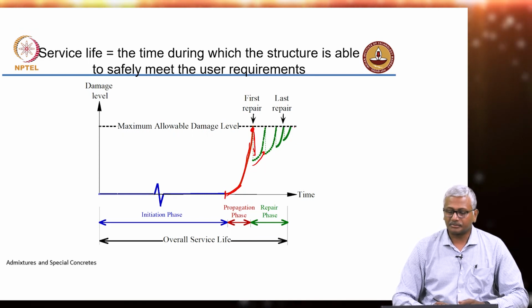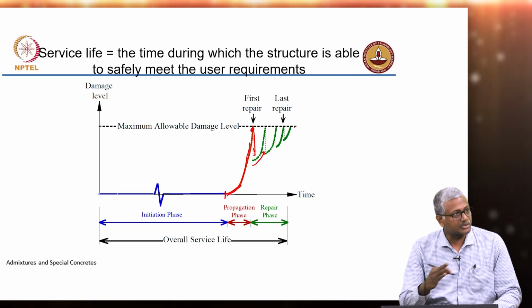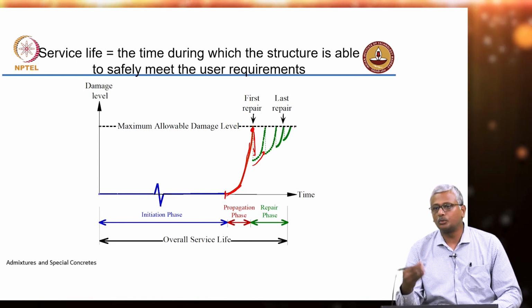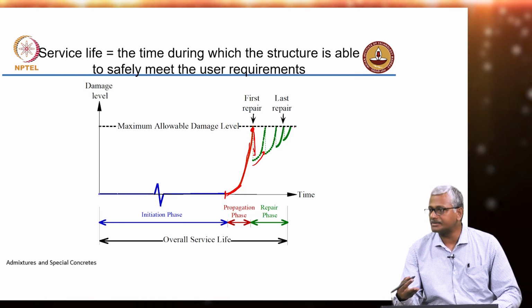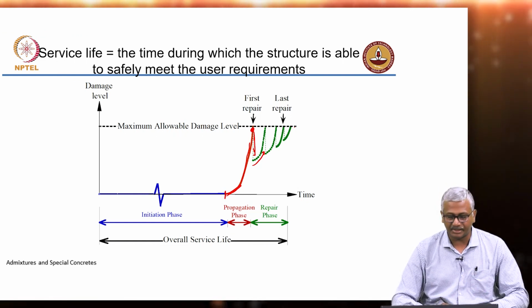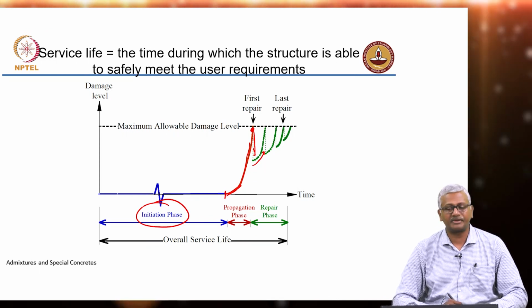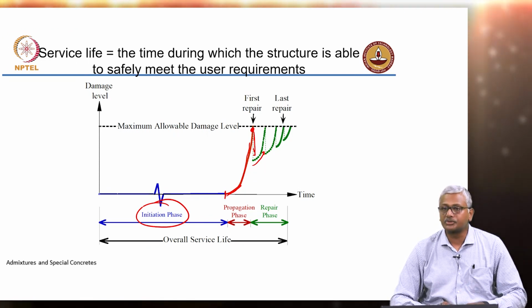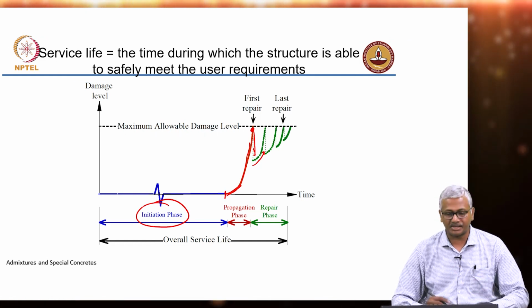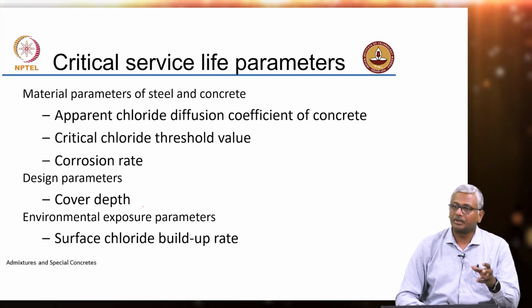Okay. So, obviously, it is very important in corrosion. If you are in those final stages, you need to do regular maintenance, regular inspections, and decide on a strategy that will further extend the service life. But what we want to look at in more detail is the initiation phase, and that is where we will make the most difference when it comes to increasing the service life of the structure. So, how do we do that?